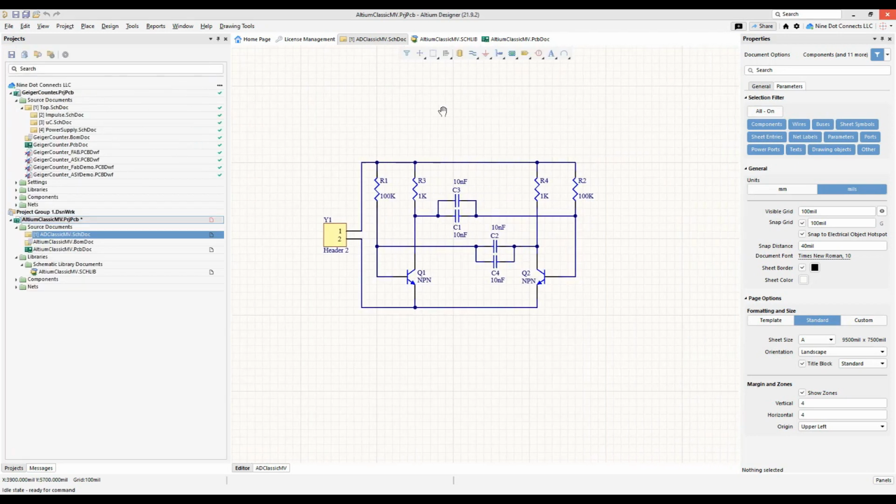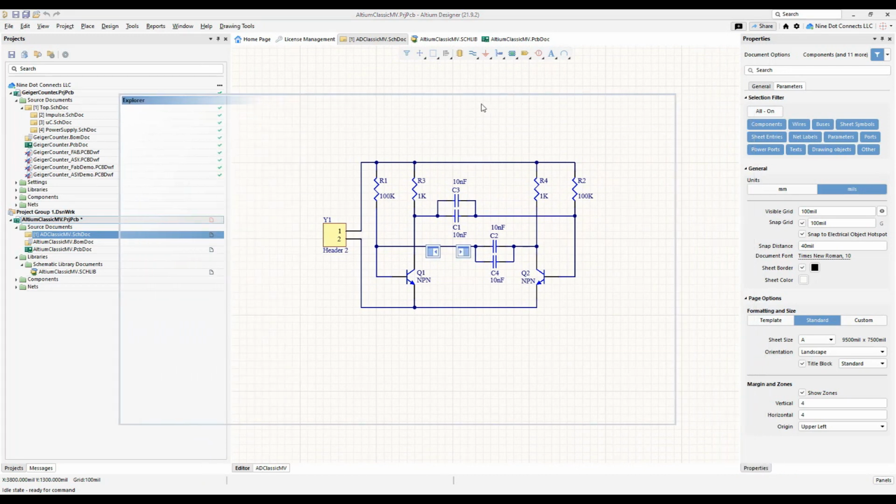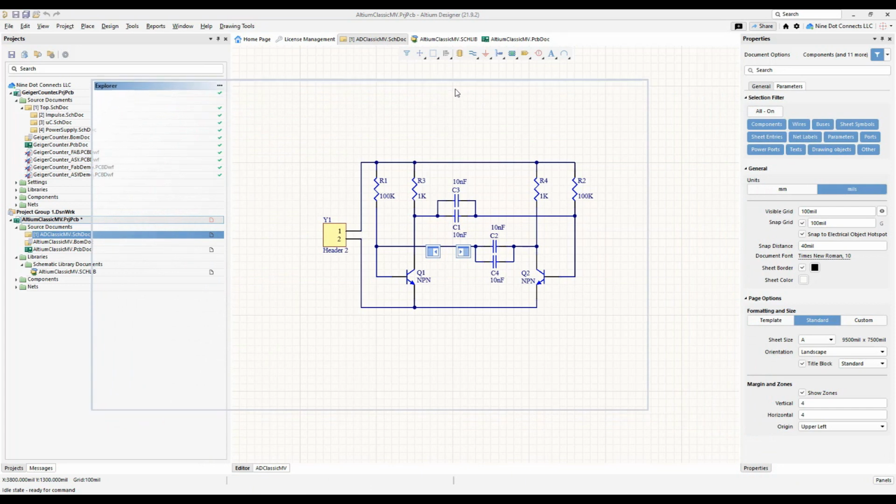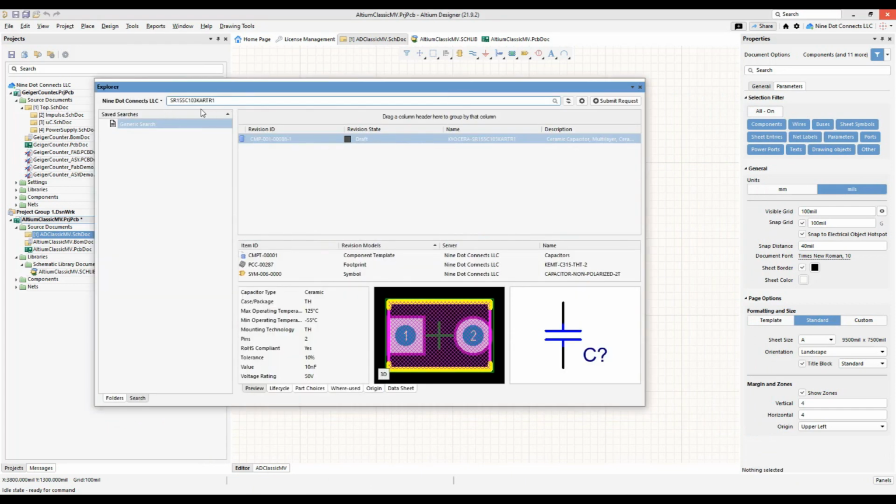So with that being said, after we created this project, I had to make sure that each and every single one of these components existed in our Altium 365 account. And just to show an example over here, I did search for this, and you can see that I have this capacitor in here. So I created it, and from there I also used the symbols and footprints, not from the miscellaneous device library, but the symbols and footprints that we already had in our Altium 365 account.